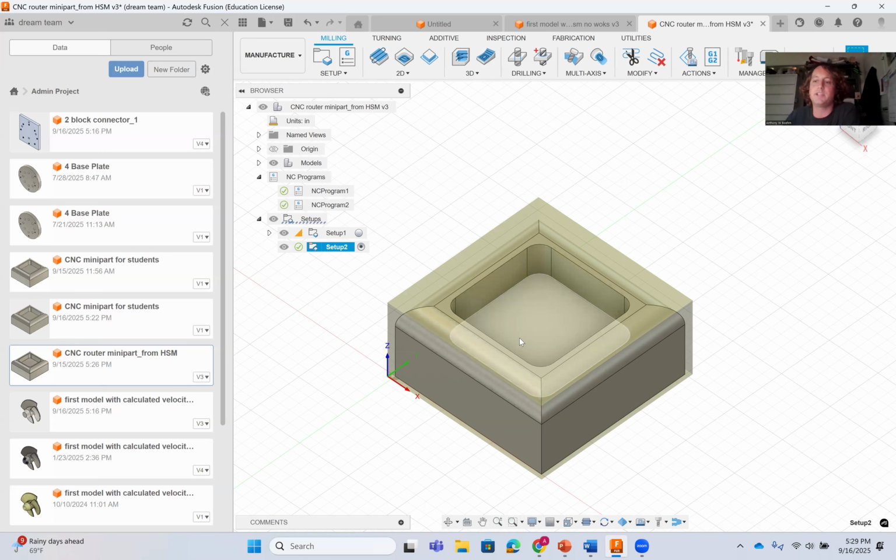It should always come to mind, whenever you're doing any sort of milling or turning operation, to think roughing and finishing. You should hit surfaces at least twice per piece, with a roughing and finishing pass, if not multiple finishing passes, depending on what is needed. So for us, we're going to try to do one roughing operation and then a finishing operation for all surfaces and contours.